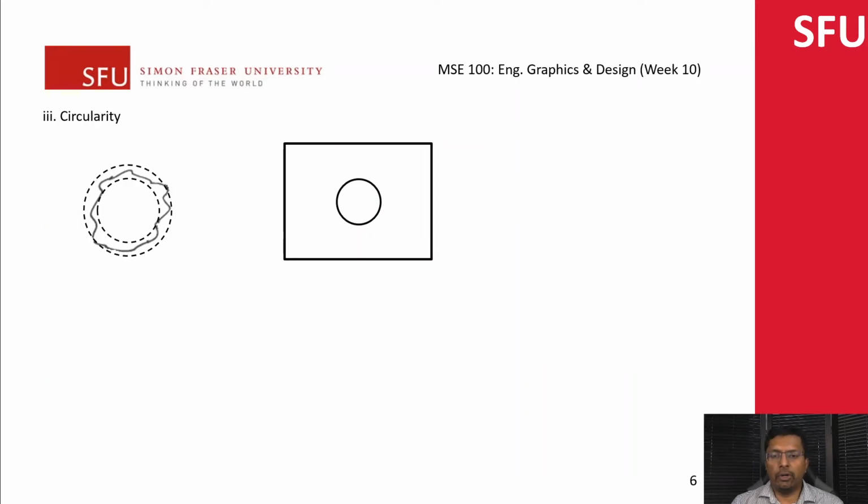So next we're going to be looking at what's known as the circularity tolerance. The symbol for the circularity tolerance is just a circle, like so. So what does it actually mean? If you have this drawing over here, you specify the circularity tolerance like so: essentially put an arrow mark, then the circle symbol and then 0.01. This doesn't really have any reference.